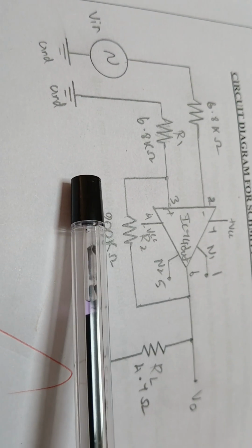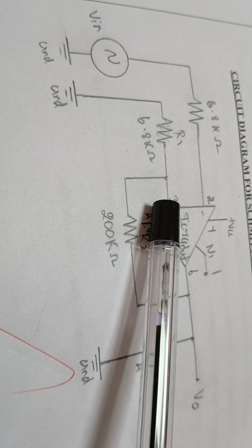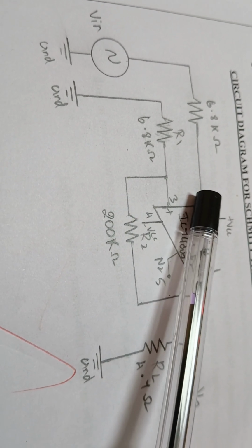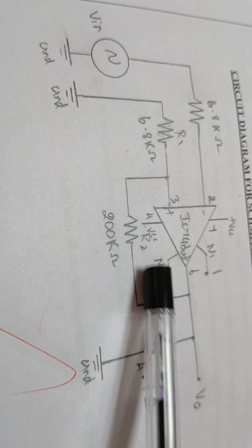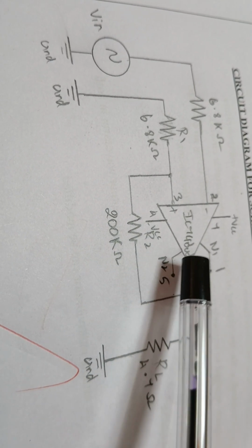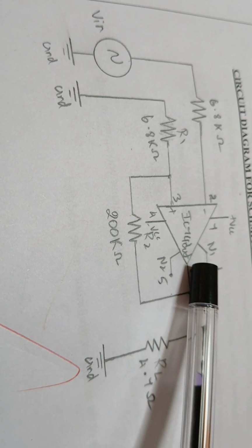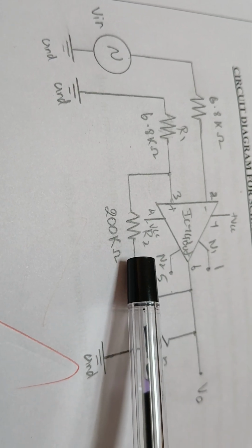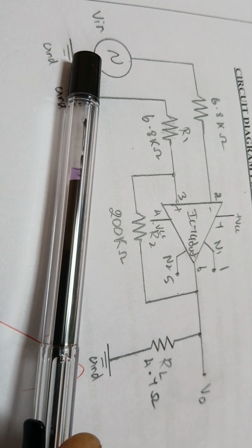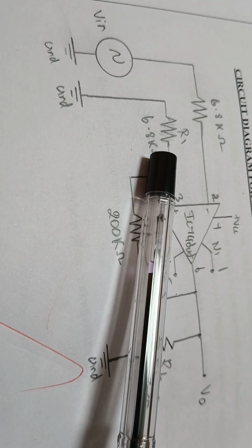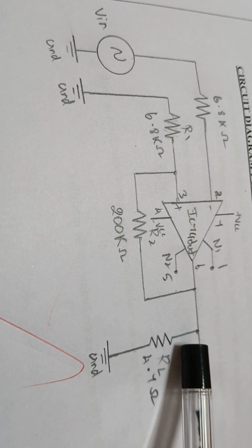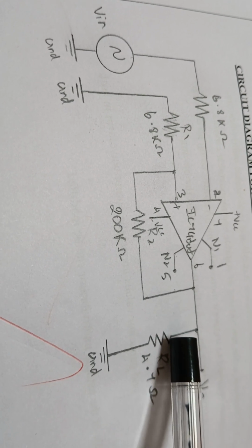When the case is reversed, that is the reference voltage is greater than the input voltage at the inverting terminal, it generates the positive going pulse. So alternately plus Vsat and minus Vsat levels are generated based on the input and reference voltages. We collect this output at pin number 6 using the CRO.